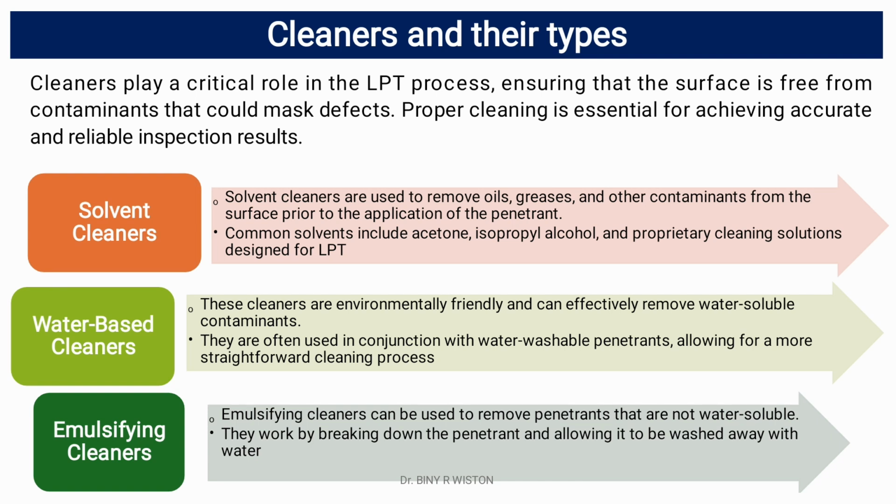Water-based cleaners are environmentally friendly and can effectively remove water-soluble contaminants. They are often used in conjunction with water-washable penetrants, allowing for a more straightforward cleaning process. Emulsifying cleaners can be used to remove penetrants that are not water-soluble. They work by breaking down the penetrant and allowing it to be washed away with water.